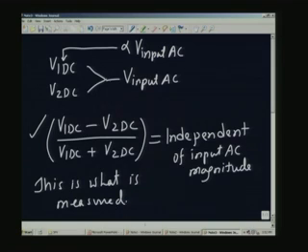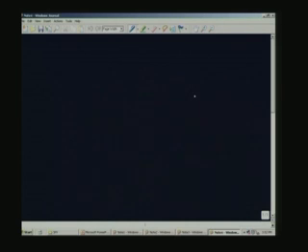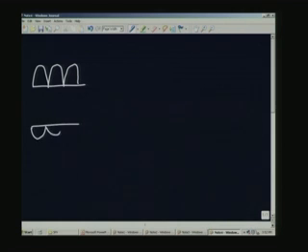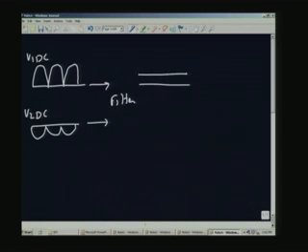So, I am not going to show the complete circuit, but what I will do is I will just show what is going to happen now. From the coil 1, I have got this, coil 2, I have got this, depending on the, this is V 1, this is V 2, DC, because I have rectified or demodulated, and I am going to pass it through a filter. So, what I will get is a voltage like this.